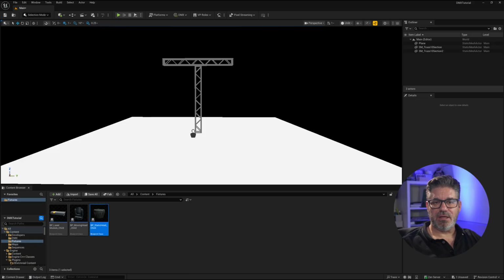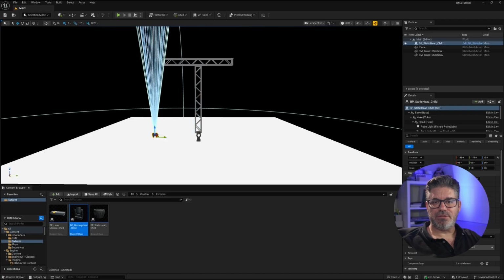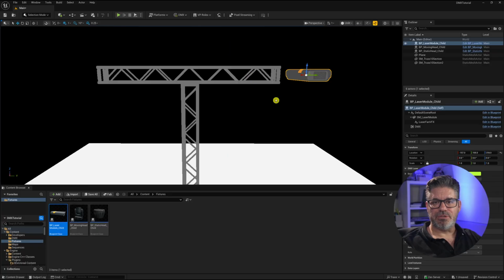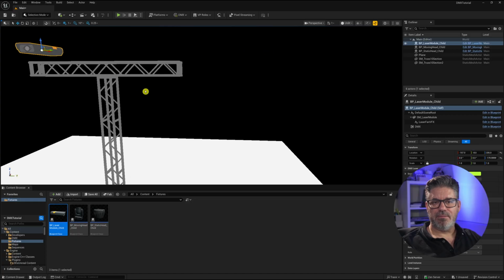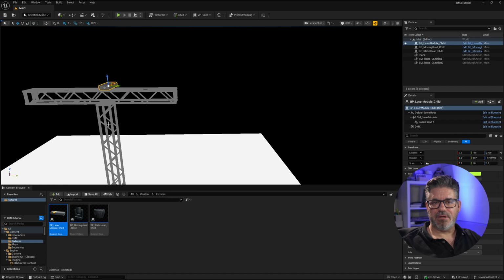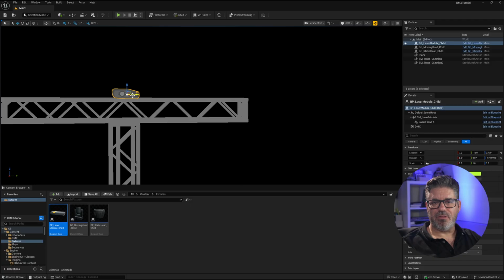We'll go ahead and move the static head, and then we'll bring the moving light, and then we're going to go ahead and bring the laser. I'm just going to very quickly put these in position. Let's drag this up here. See, this is where 2 helps me just to jump in quickly. I'll rotate it around. Okay, I'm going to move it up here. I'm going to have to adjust my camera angle over this side because I can't see how far back I am. But again, just go ahead and hit that key. All right, let's just nudge it into place there. Let's go ahead and hit that key to jump all the way out.